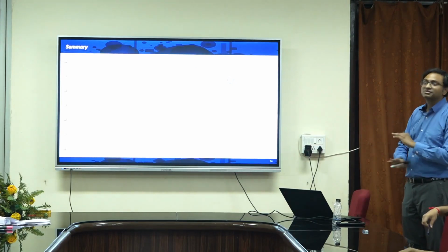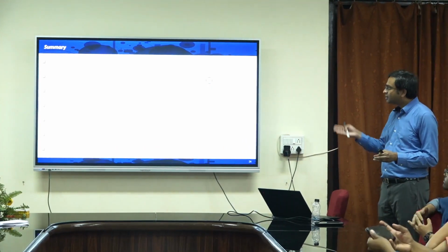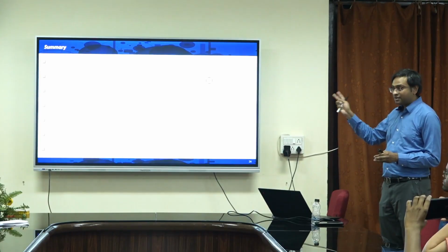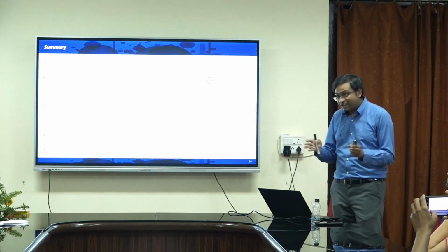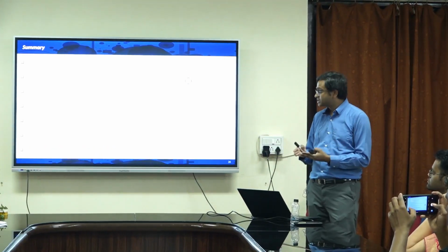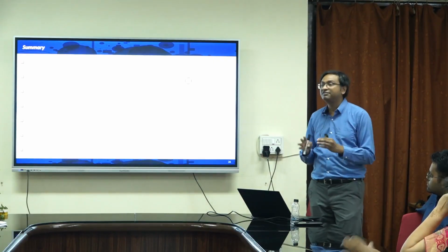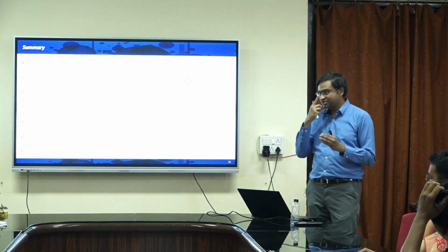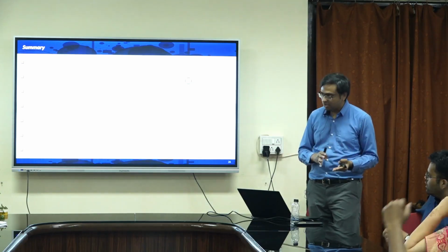So contacts are absolutely important, and they are even more important for a scaled device. Second, contact resistance increases as I scale my contact, which is counterintuitive to what happens to the channel. Third, 2D metal contacts on top of that suffer from Fermi level pinning, so just metal work function engineering cannot rescue me to get to an ohmic contact.